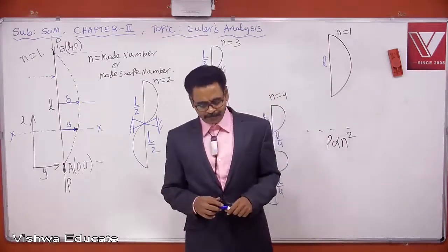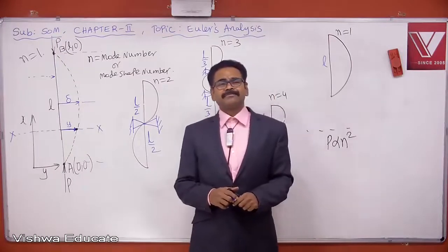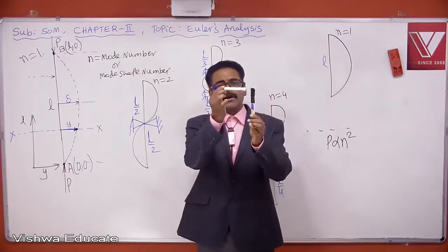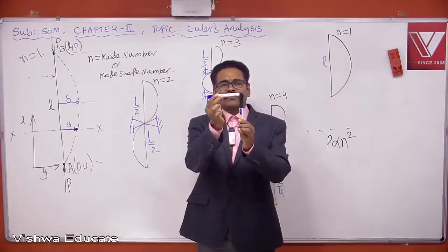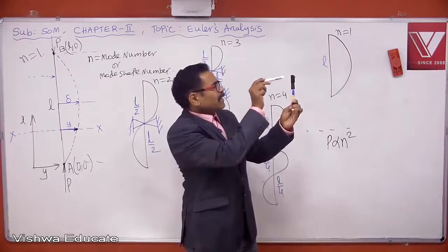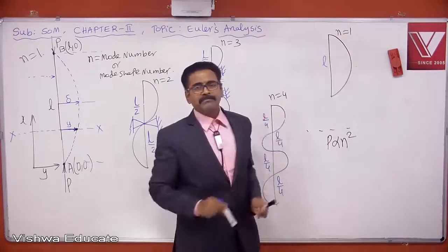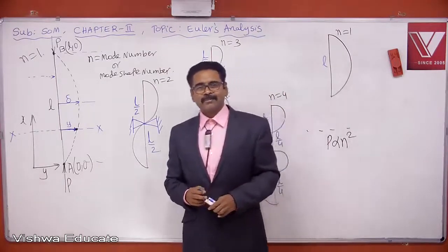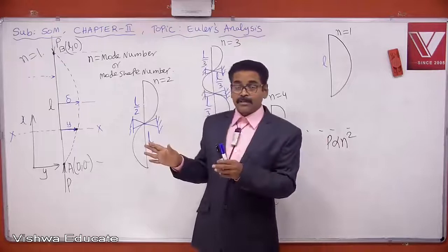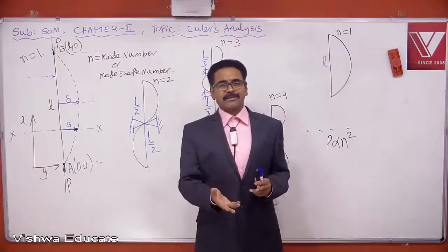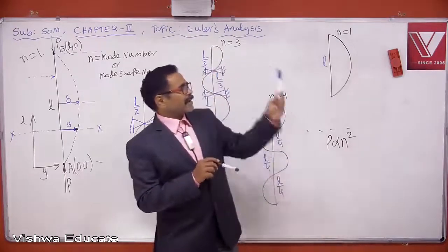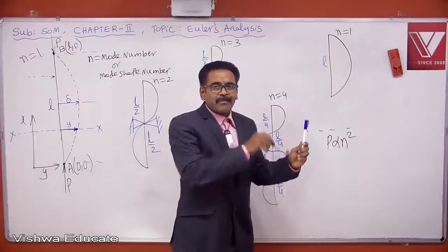And second point, usually in construction of buildings, first you construct columns, then you join all columns by horizontal members. These horizontal members are beams. All columns are connected by beams. With respect to a column, what is a beam? A stop. When the column tries to buckle, the beam will try to resist. Of course, I should not say full stop. It is a partial stop. So with respect to every column, a beam is a partial stop.